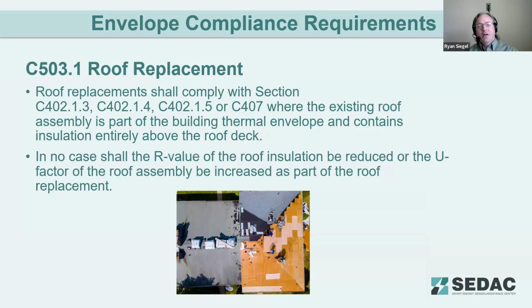When doing a roof replacement, it needs to comply where the roof is part of the building thermal envelope and the insulation is entirely above the roof deck. This is typically found on low-slope roofs. This is calling out that you need to bring the insulation value up to the current standard during a roof replacement, not a roof recover.